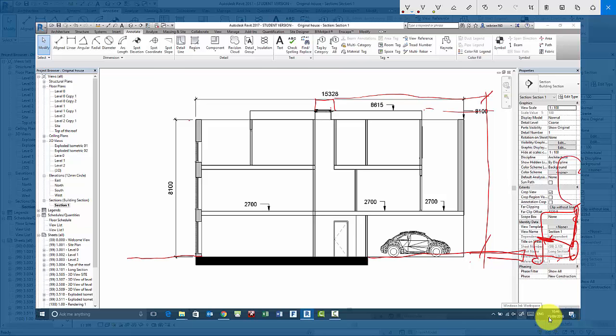So I have done schemes where we had to do the entire technical drawings based on this dimension that had been limited by the local authority, and we actually had to name it to the builders as the most critical thing in the entire project, that you don't go beyond this point here. Because if you go beyond that point, you will be breaking the application requirements, which means the local authority actually has the right to tear the entire thing down. It seems stupid, but that's just the way it is.